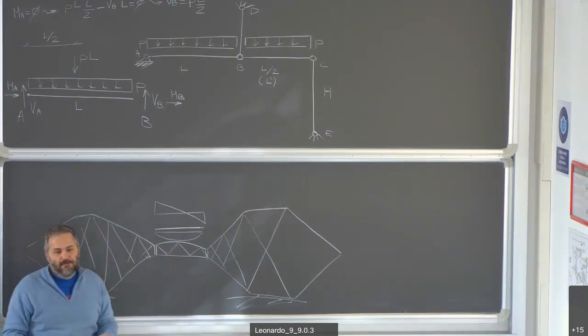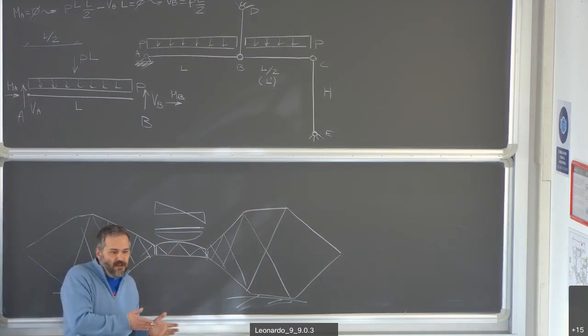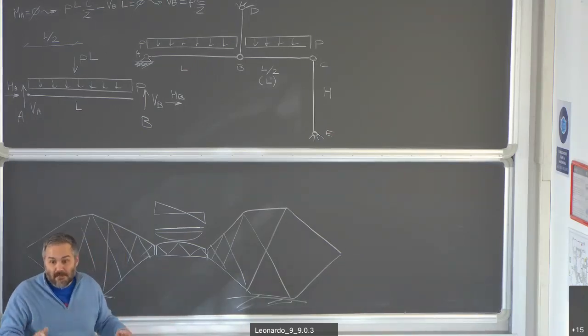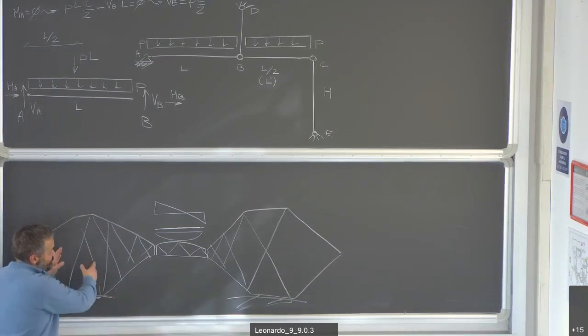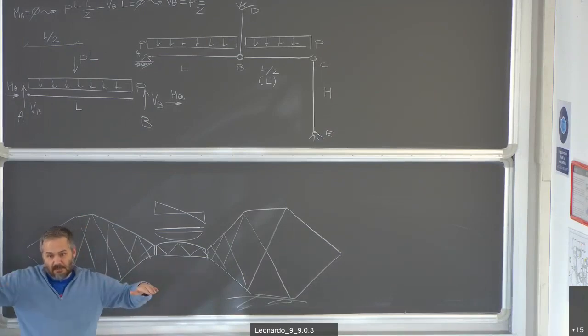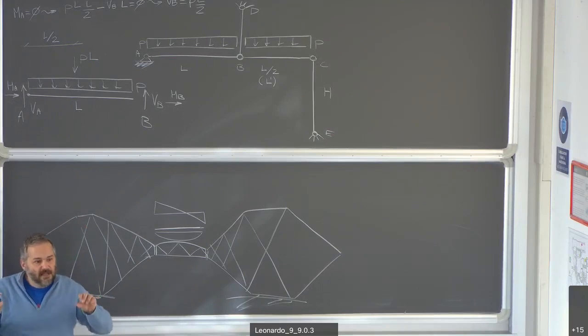Other example, you may be familiar with the bridge that failed in Genova some years ago. The Morandi Bridge. Morandi Bridge was exactly the same. The concept was exactly the same. We had big antennas where the supports were, then there were those ties that kept up the bridge, and in the middle was a smaller portion of concrete which was basically put there and simply supported. And that is why it failed.